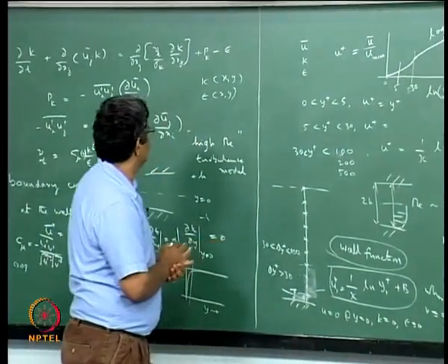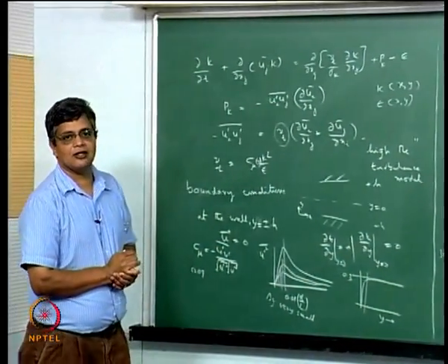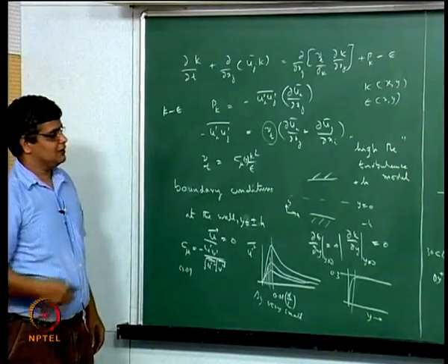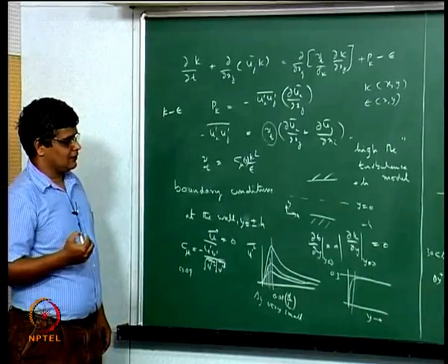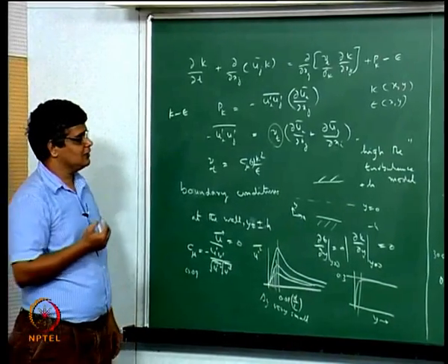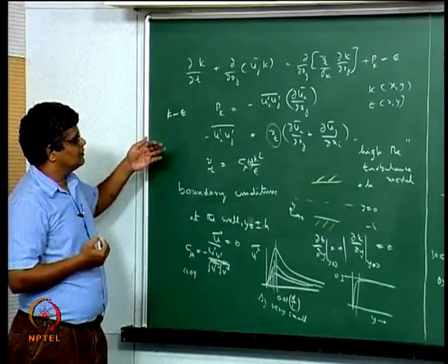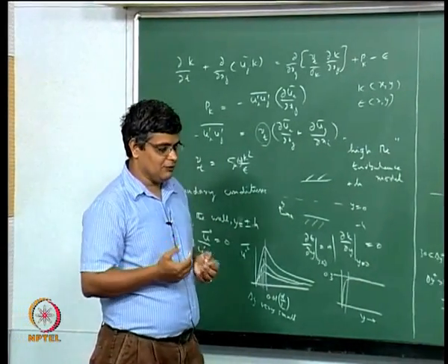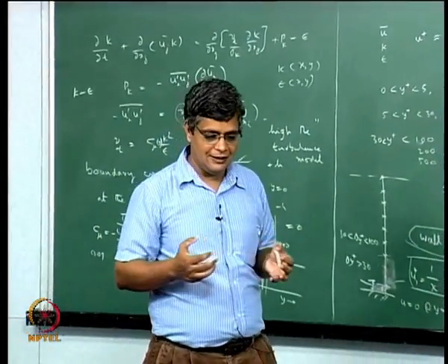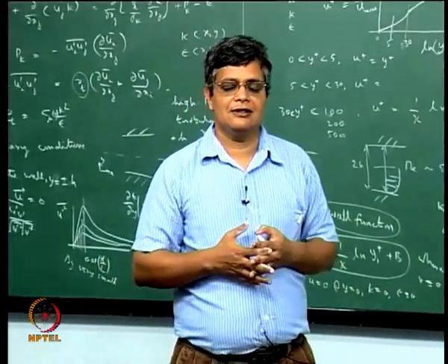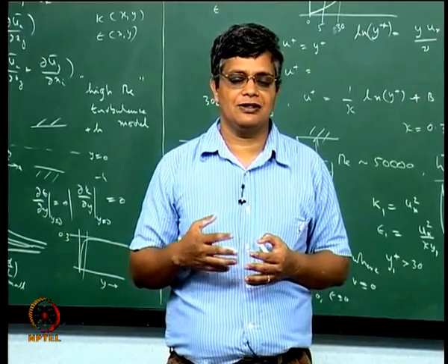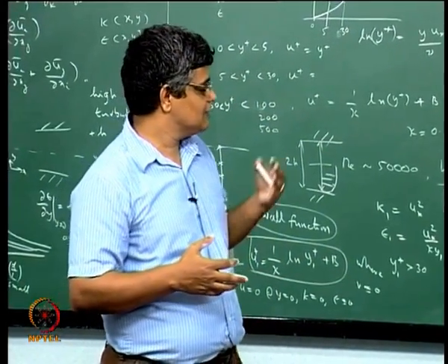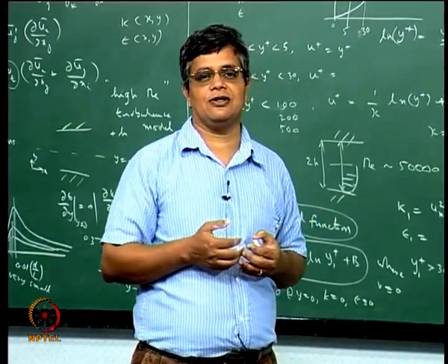Otherwise we have this fairly universal model, the k epsilon model, which can be used as a first attempt to calculate the turbulent flow without having to fix any constants. But even though this is considered a fairly general model, there are modifications to this, for example, for strongly accelerating flows and for buoyant flows, and in such cases people have come up with a different set of constants.